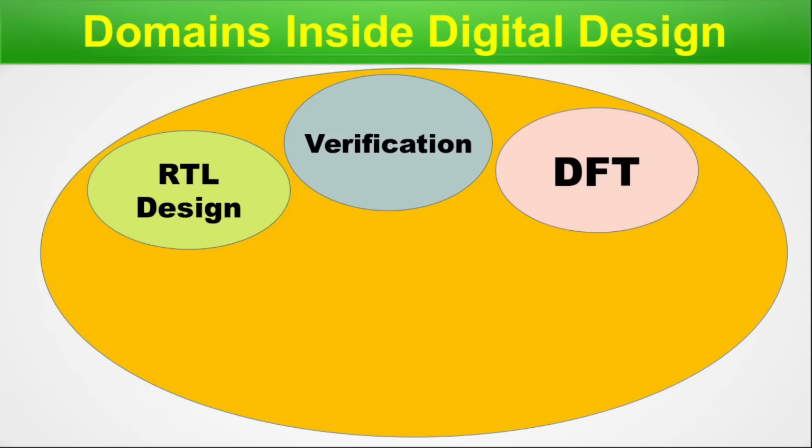Next comes the domain for DFT, that is Design for Testability. Here you deal with IC design techniques implemented inside the chip to conduct manufacturing tests. For this, you must have skills in software such as TetraMAX, DFT Compiler, etc. You will come across terminologies such as ATPG, ATE, BIST, MBIST, JTAG, etc. as skill sets for this DFT domain. Up to this point, we were at the front end.